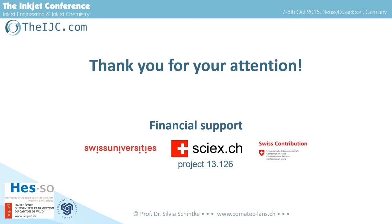Influence of the moisture of PEDOT? Okay. These measurements have been done in normal conditions, in fact, so we have not really looked at humidity effects. And concerning the interface resistance, our model can be completed with a resistance for the interface between the indium tin oxide and the coating layer, but it would also be eliminated by the subtraction of the two test structures.